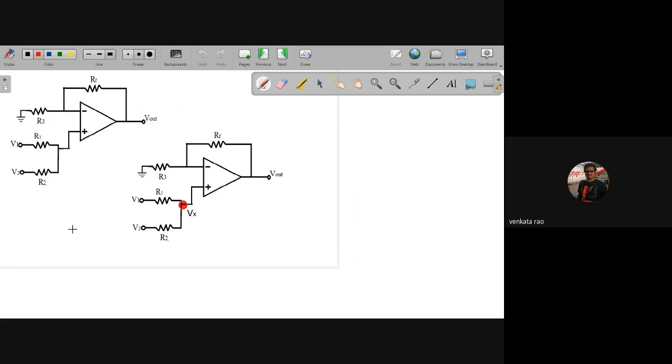See this? In this, now two signals are applied at the non-inverting terminal. Except this part, if you verify, this is a non-inverting amplifier, we know that. So output voltage is always 1 plus RF by R, here it is 1 plus RF by R3.